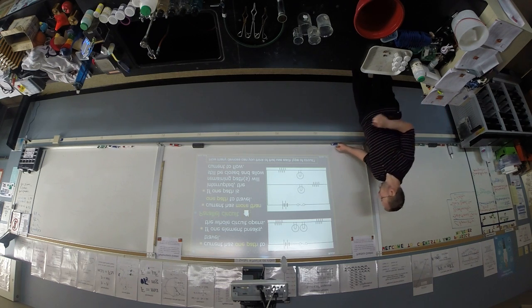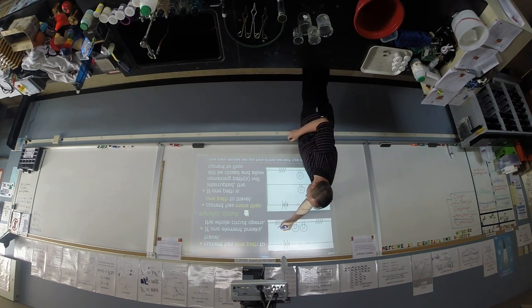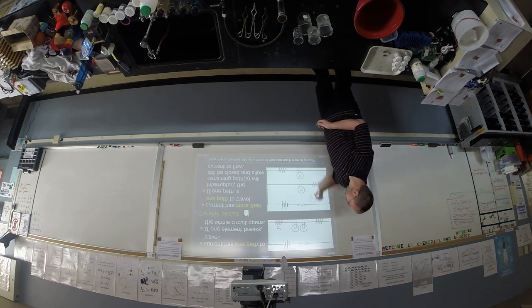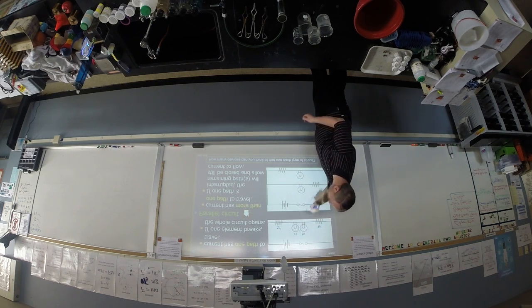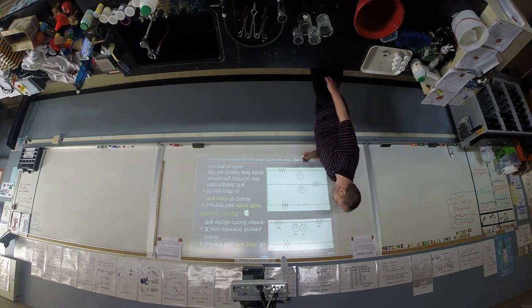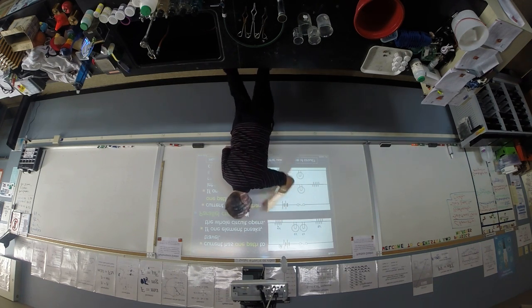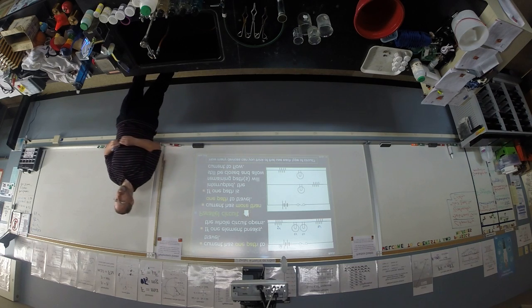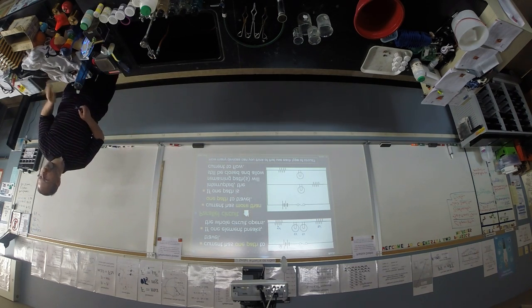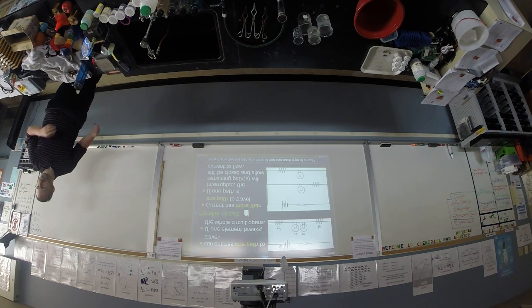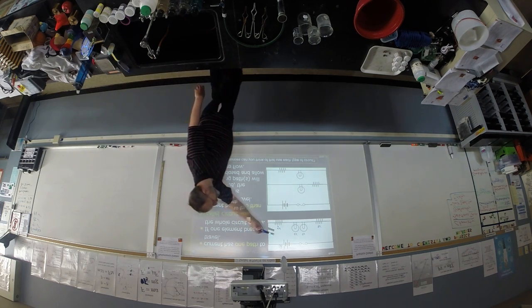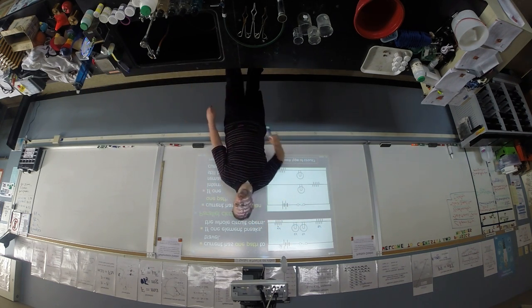Now what does that mean? If this resistor gets 2 volts, and this resistor gets 3 volts, and this light gets 4 volts, and this light gets 4 volts, that means the battery is pumping out 13 volts. That's just the total of all. Yep. The battery is the total of all the voltages in each individual device, as long as you realize it is the battery that's producing the voltage, not the device. So the total voltage in the battery is divided amongst each individual device.